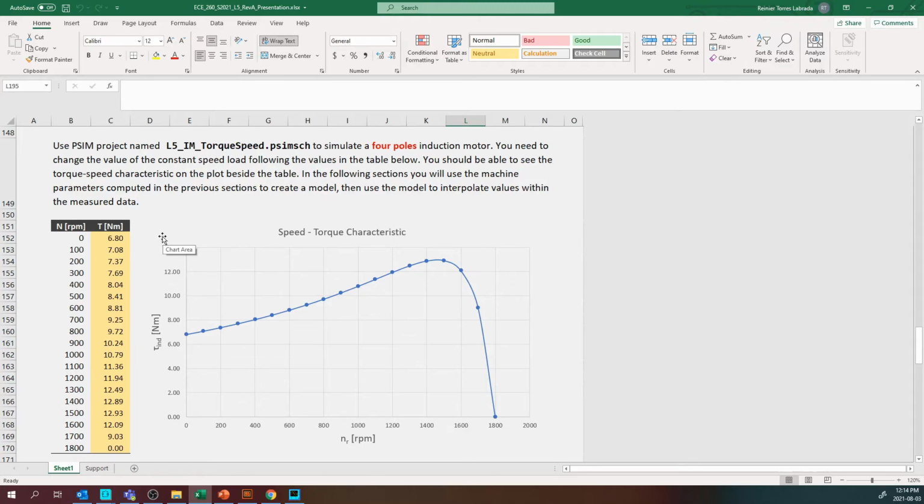Imagine you have a big motor. Running a blocked rotor test on big motors with a dynamic load is not easy at all. You can pretty much block the rotor if you really want to, but that can be very, very expensive because you're going to need a huge mass so the motor doesn't move to run this test.